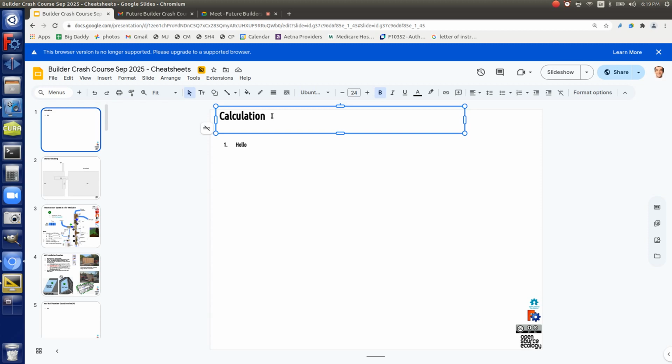Wood, steel, and concrete. So actually we should add concrete, which is like rock, on a scale of several thousand pounds per square inch of force that you can load onto a piece of concrete. So think about that. Per square inch, 3,000. If you get a piece of wood, compressive strengths can be, let's look at the big figures. For steel, it's in the tens of thousands to 100,000 psi.